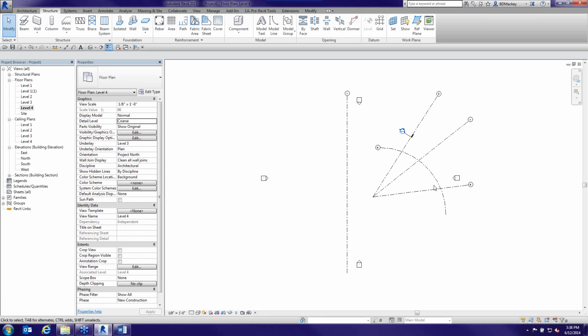I have been in my career adjusting so many levels and grids to match the 3D extents that I cannot believe I did not think of this earlier in my career. I know there's been a couple buildings where there were 2 towers coming off one building, and I worked with a guy for 4 hours having him clean up all the levels for Tower 1, all the levels for Tower 2 to get them the right 3D lengths. I could have just created a scope box and been done with it. So just think about those scope boxes as more than just being able to set your floor plans up correctly. Allow those to go in and set the extents of your levels and or grids.